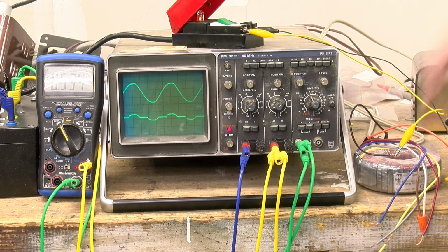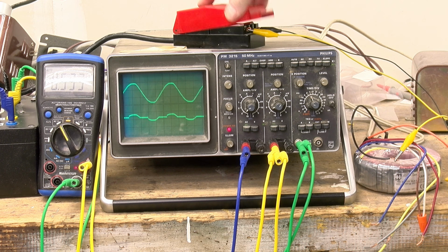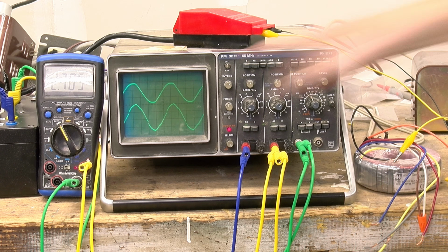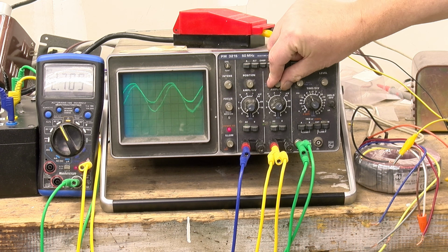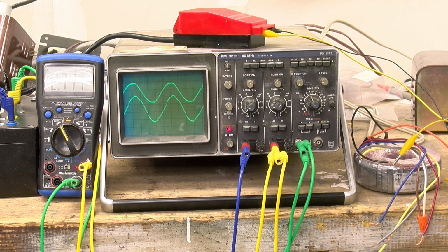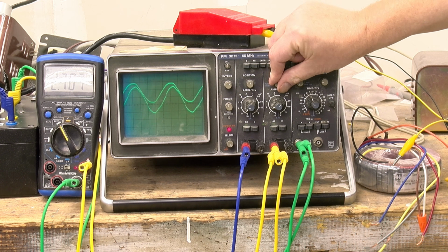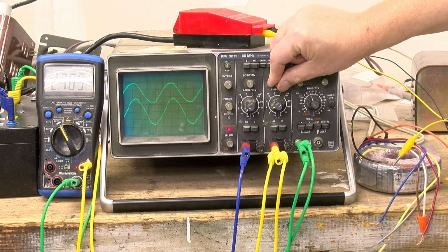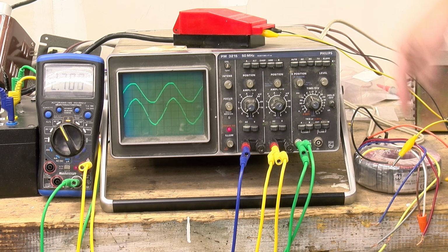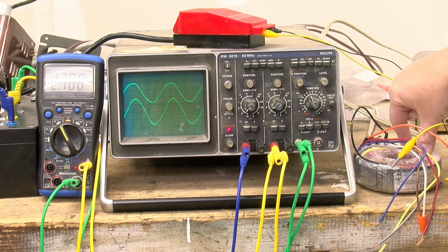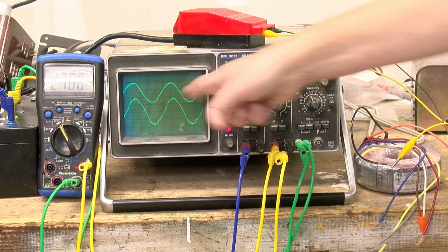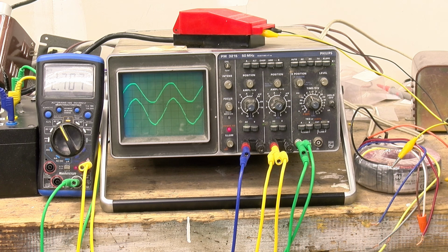Okay, so I will disconnect our test leads, and now I will hook the test leads to the toroid, the transformer, and we'll see what we get through it. Well, we get a somewhat nicer waveform, and if we compare it to the incoming AC waveform, it is lagging the AC waveform. It's not lagging by a full 90 degrees, and that's because there's a fair amount of resistive or mimicking resistive losses in the core, which adds a real current. So it's probably lagging by about 45 degrees or something like that, as opposed to the full 90.